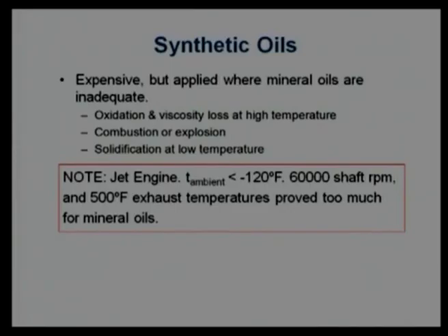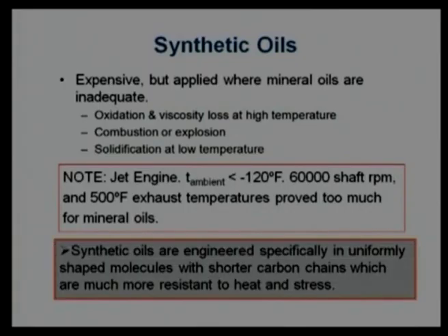In this situation, mineral oil with all kinds of additives may not give desirable results to us. And that is why I say that synthetic oils are engineered. Reason being, as they are engineered, they will have uniformly shaped molecules. That is why we will have much more robustness than mineral oils.